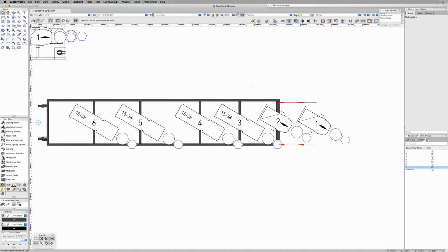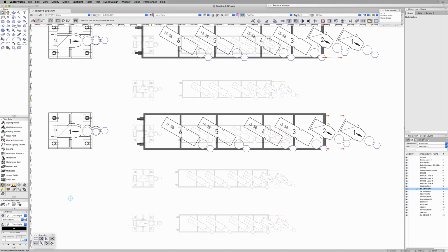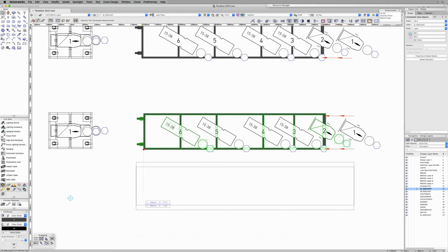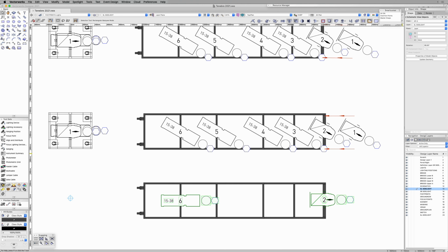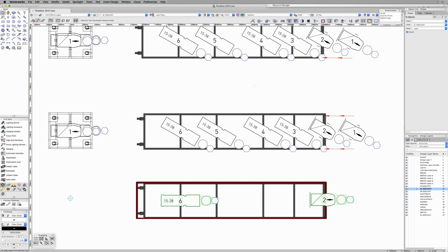The Spotlight numbering tool works well with schematic views, and once you get the hang of the process, you can actually have schematic views of custom positions set up in no time. If you use boom shadows, then the schematic view object can also be quite useful. If you drag a copy of the object away from its original, along with maybe two of the lights, rotate the lights to 90 degrees and then ungroup them. All the geometry remains, but the interactivity with the original object is lost.